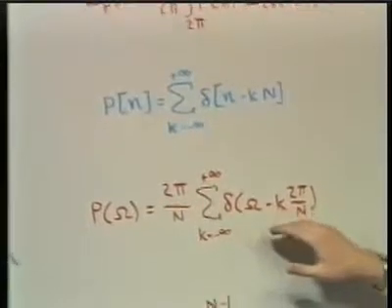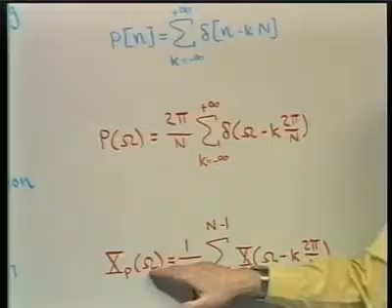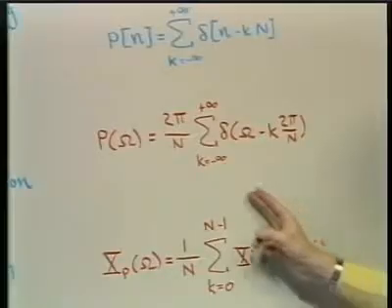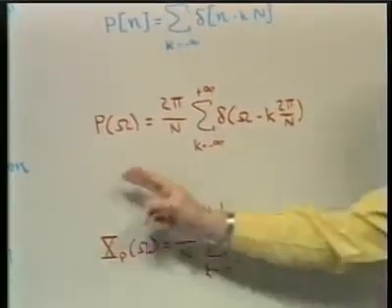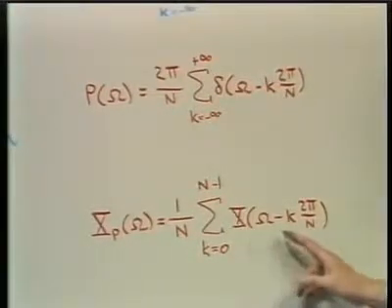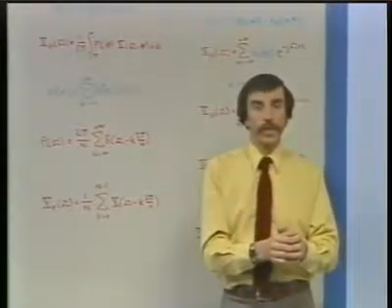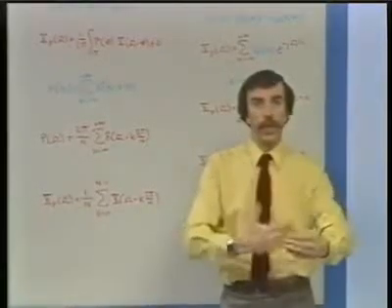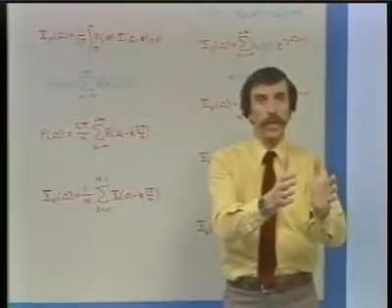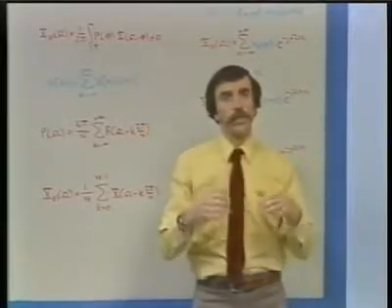And now, finally, the Fourier transform of the resulting sampled sequence, being the convolution of this with the Fourier transform of the sequence that we're sampling, gives us then a spectrum which consists of a sum of replicated versions of the Fourier transform of the sequence that we're sampling. In other words, what we're doing, very much as we did in continuous time, is through the sampling process, when we look at it in the frequency domain, taking the spectrum of the sequence that we're sampling and shifting it and then adding it in, shifting it by integer multiples of the sampling frequency.